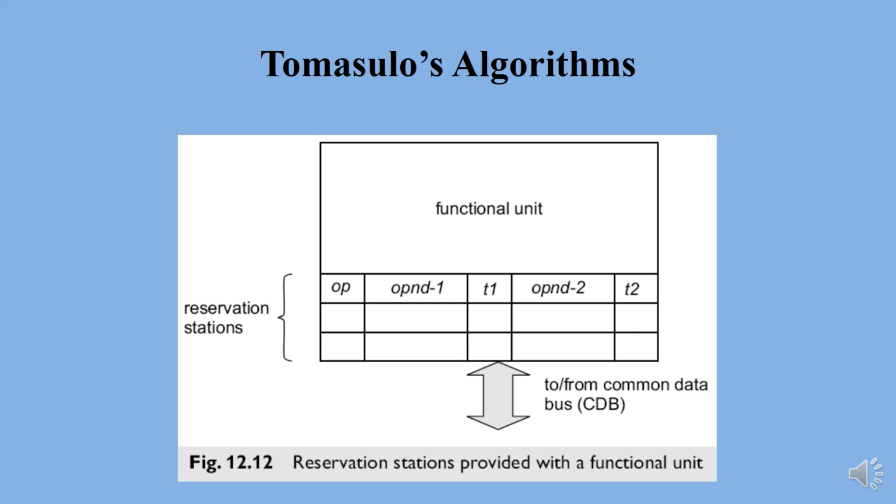As soon as the required operand value is available at its source, which would typically be the output of a functional unit, the data value is forwarded over the common data bus along with the source tag. This value is copied into all the reservation station operand slots which have the matching tag.